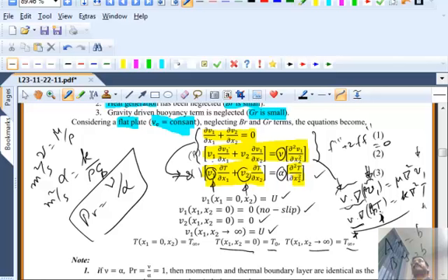So that means that a fluid that has a higher kinematic viscosity can send its impact deeper into the boundary layer. Remember, the boundary layer thickness is proportional to the kinematic viscosity. So honey will have a thicker boundary layer than air, right? So it is proportional to that transport quantity. When the transport quantity is thermal diffusivity, then the ability to transfer heat depends proportionally on alpha. And because most fluids don't have the same property values, that is, the Prandtl number is not 1, you don't have the same boundary layer thickness.